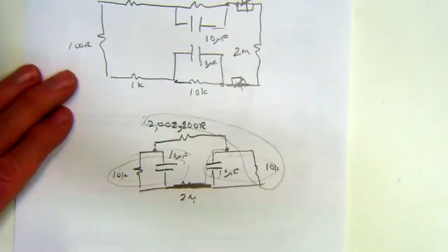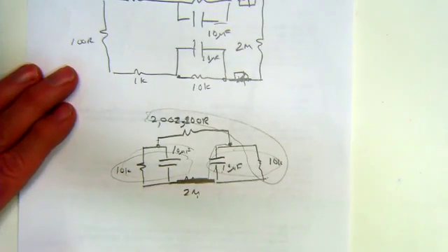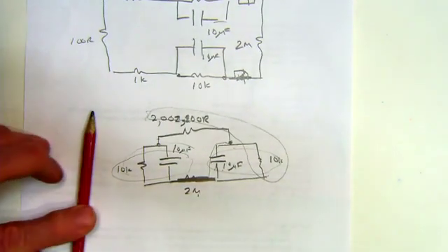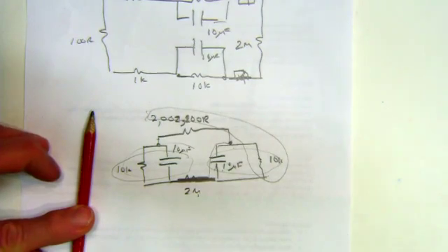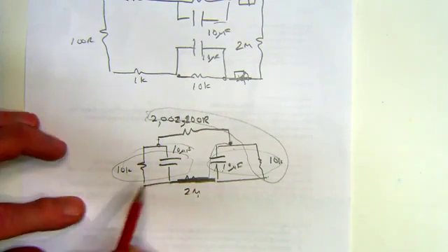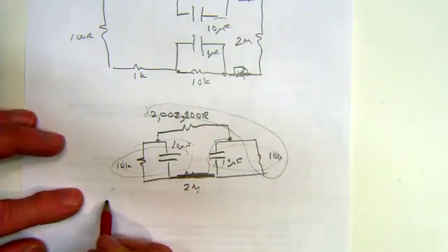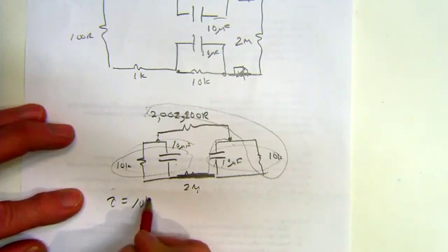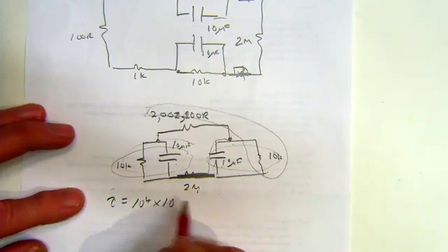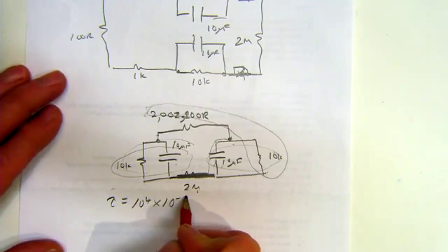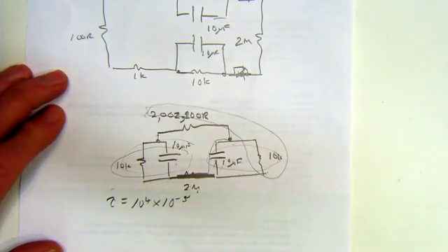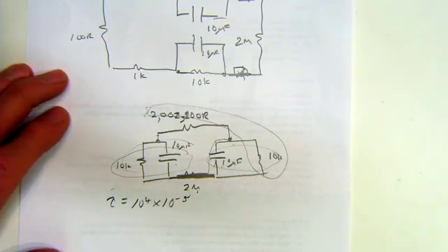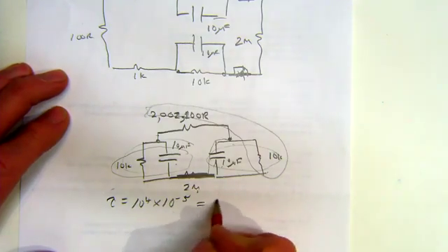So ultimately, at the end of the day, I'm sorry this is hunting around a bit. It's better to put something there to focus on. So all we really need to do is figure out the time constant of these 2 components, which is 10 to the 4th by 10 to the minus 5. Am I right? Yes? So 10 to the minus 1.